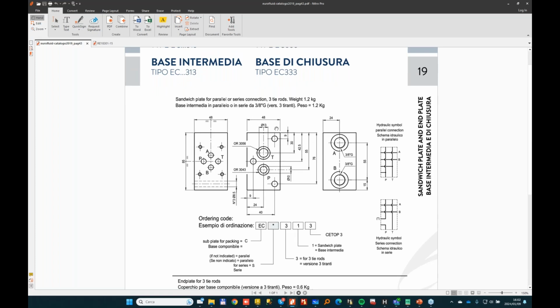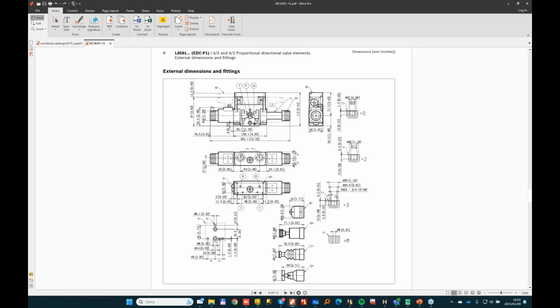I'll try to make a small exercise explaining how to efficiently design a custom mid inlet serving these two elements: one sectional valve and one on-off subplate. I also drew a small end plate just to cover the left side of the Bosch Rexroth working section.